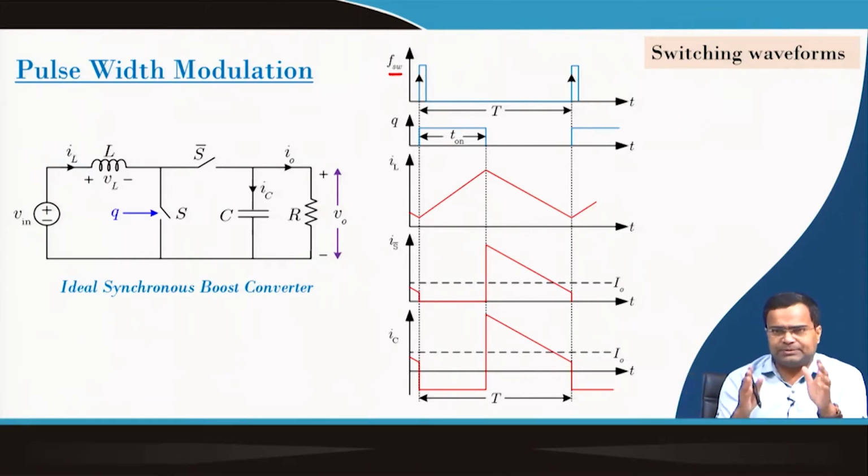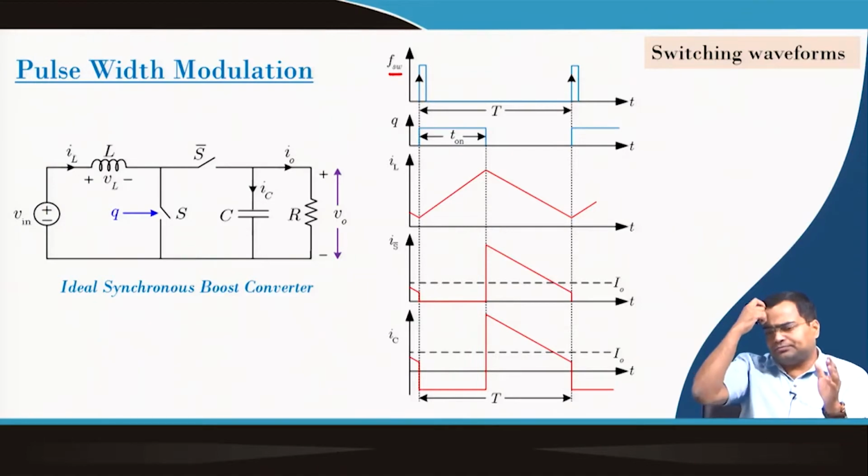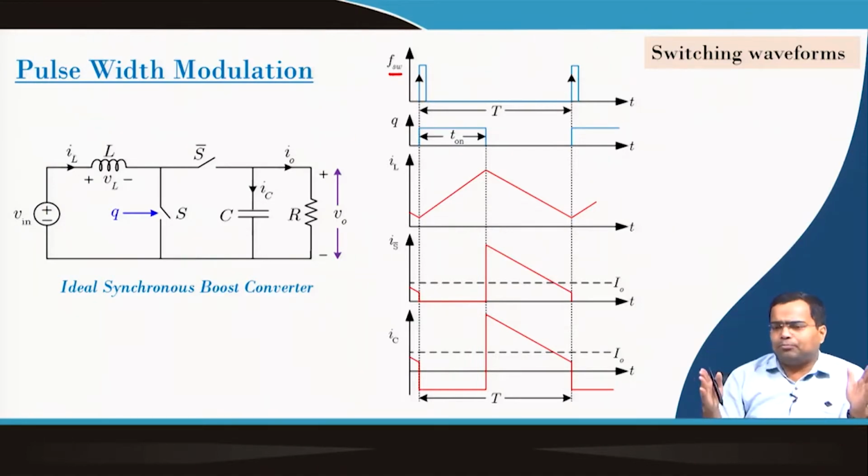Okay. So, the clock is a fixed switching frequency clock, but we can program this frequency according to our requirement, provided that it satisfies the design constraint of the converter, because when you design a converter we need to know what the switching frequency is, or we need to set some switching frequency. Accordingly, we design the inductor, capacitor and all this.